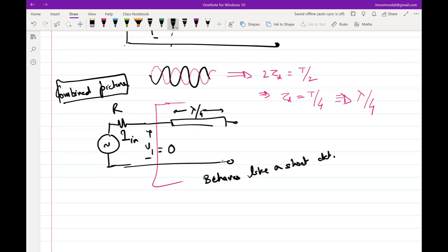You are going to see later on where these are used, but I am not proving those. Those are textbook stuff. You can also do it yourself without going into the hyperbolic formulas. You can do it by this multiple reflection approach, and that's a very good exercise. It gives you a lot of intuition, and you can do these simulations in Cadence or any other simulation software. You apply a pulse and see the reflections. It's very interesting to see that these transmission lines are not really theoretical concepts. You can actually see wavefronts moving.